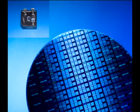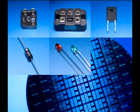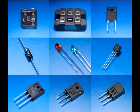When it comes to semiconductor products, including thyristors, it is important to guard against static electricity. Static electricity has a small amount of current, but the voltage can be several kilovolts or more. People are usually unaware that they have picked up electricity, making it possible for several kilovolts of static electricity to accumulate before they know it.